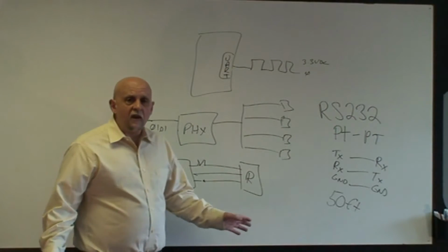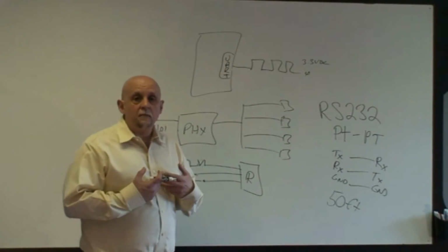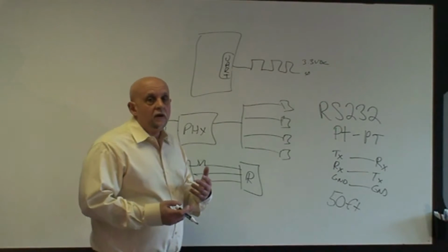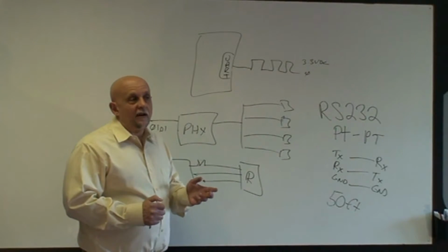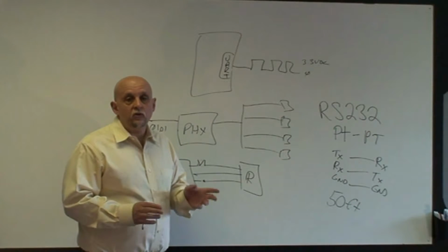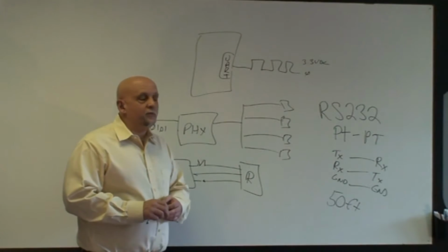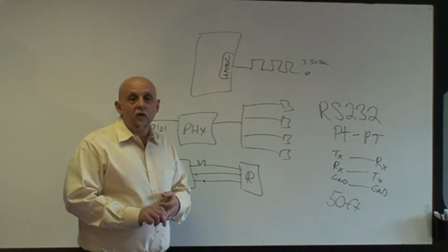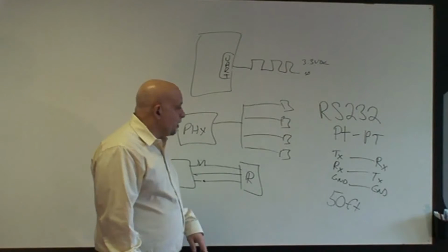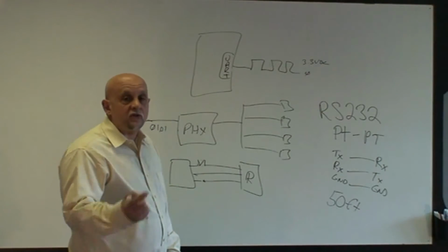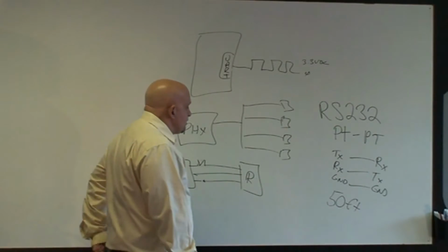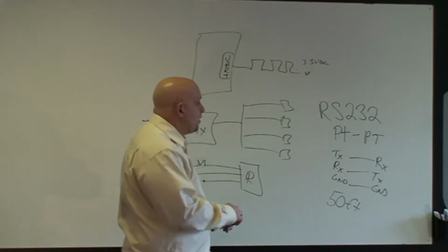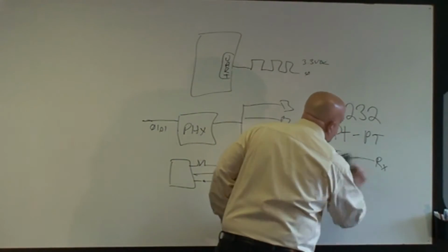In our factory environment, like the products that RTA makes, RS232 is very seldom used. It's only used when we're pretty confident that we aren't going to see a lot of noise or a lot of errors. If you do, then we have to do something else. And the other thing that's typically used is RS485. So let's take a look at the characteristics of RS485.